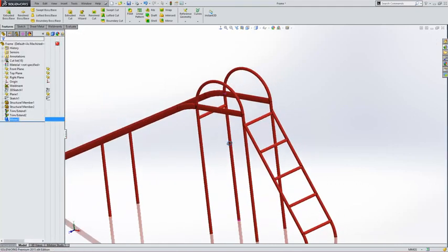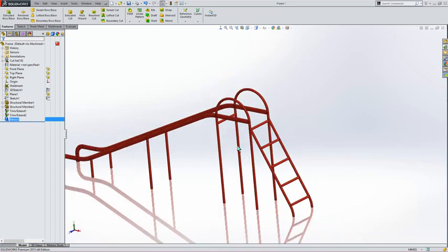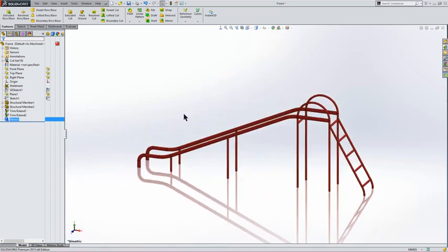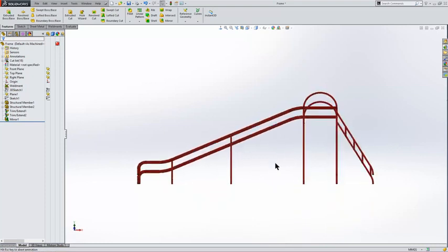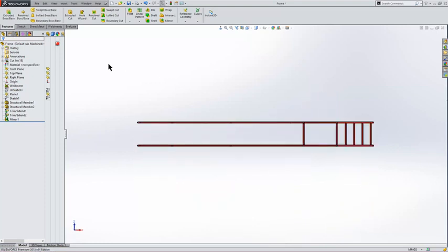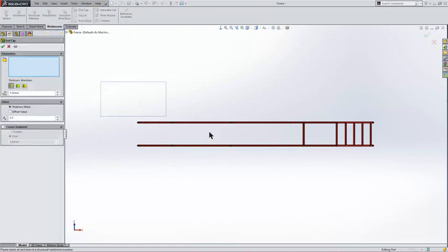And we've got a nice, strong frame here that's going to hold our slide. Some other things we can do, we could actually add end caps to the bottoms of our weldment frame. So end caps are easily done. We'll just do a group select over the faces on the bottom. Takes a little bit to think, but we can have a look to the left hand side and see what types of end caps we can do.